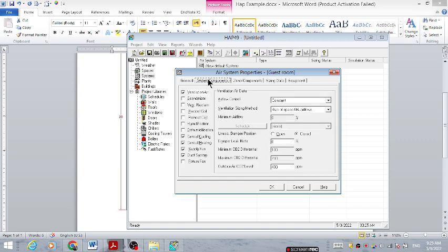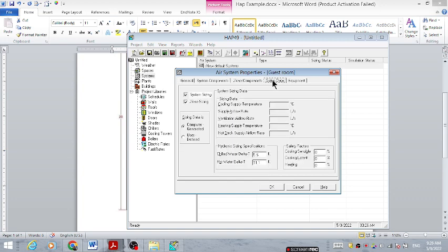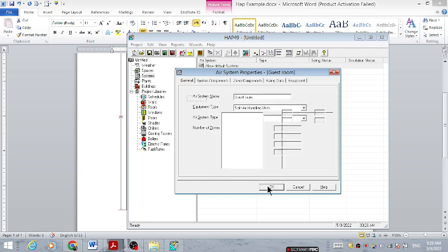Okay, system component. What do you need to calculate this information? Ventilation, air. This is sort of information for researchers, students. Zone component. Which zone? If we have more than one space in the building, which zone do you need to calculate the cooling load for? For this example, I have only the guest room. Add it here to design the cooling load for it. This, don't play with it. Okay, all set. Hit yes.